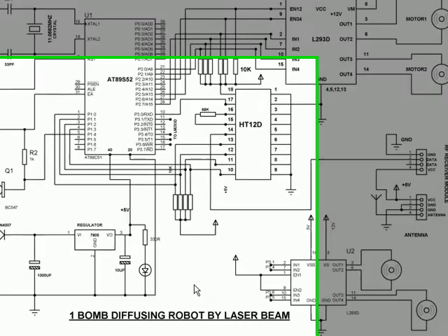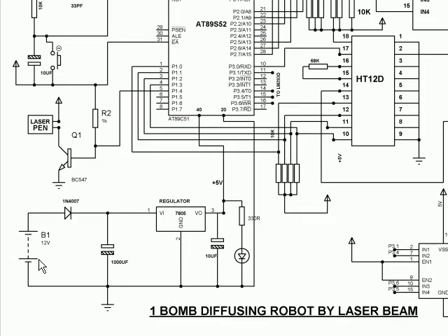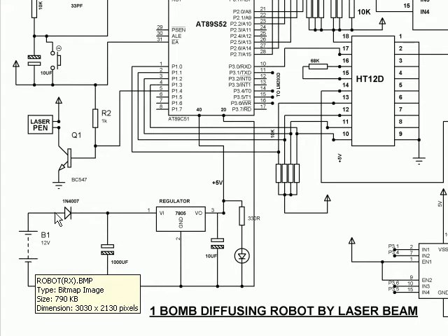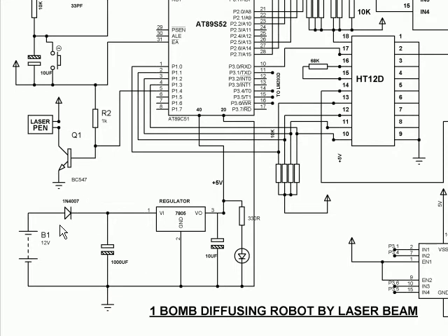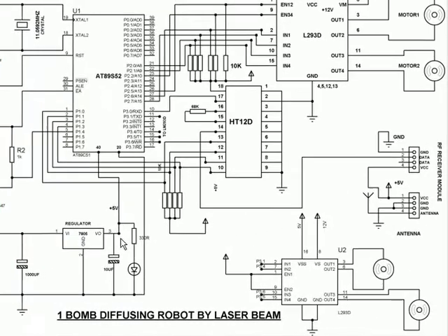And the components that you use is first a power supply, we have a battery, and then we have a blocking diode. By chance, suppose the battery is reversed, the blocking diode serves the purpose of protecting against any reversal of the DC power supply. We have got a filter capacitor here, because any noise, if at all being superimposed, would be filtered here. And then we have a voltage regulator IC here, 7805, which delivers 5 volt at its output, because 5 volt is required for the microcontroller and for all associated circuits.